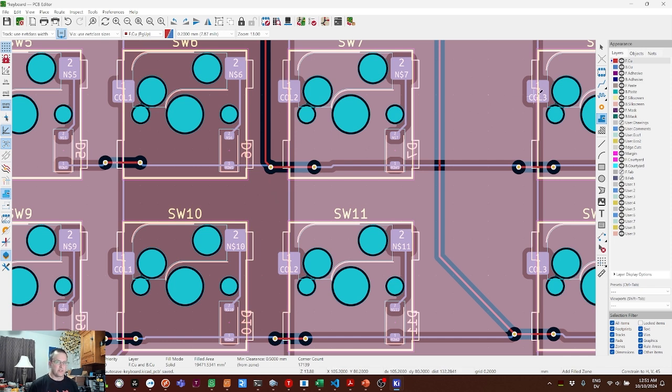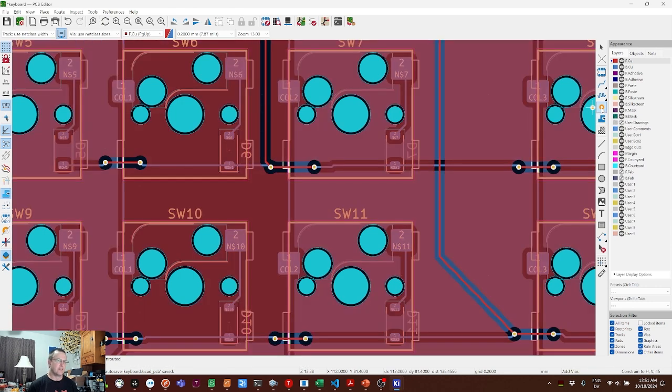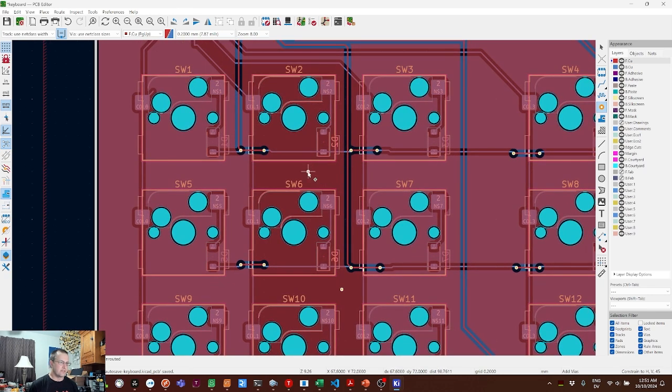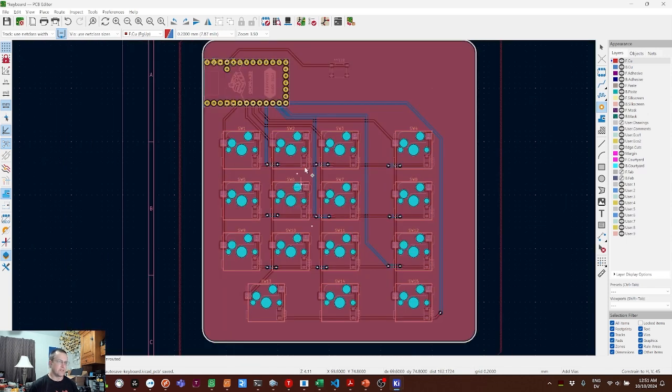We can connect the two ground planes together with what's called a stitching via. It's not going to be a regular route via like we did before, but in the toolbox over here, we can click Add Vias, and then we can click somewhere in this area to stitch the two areas together. And we put one there and one there. Then we hit B and see what it looks like. Yep, that was enough to connect the front and back together and fill in more of our ground plane.